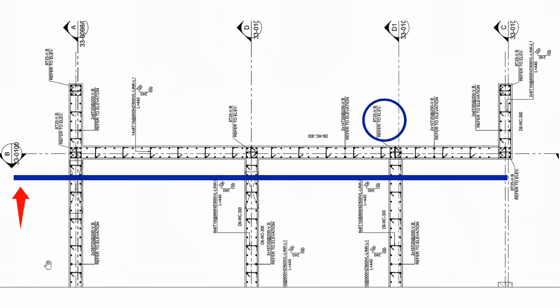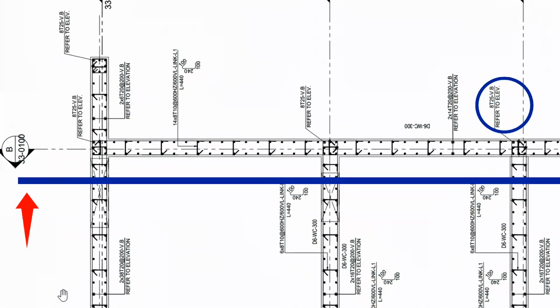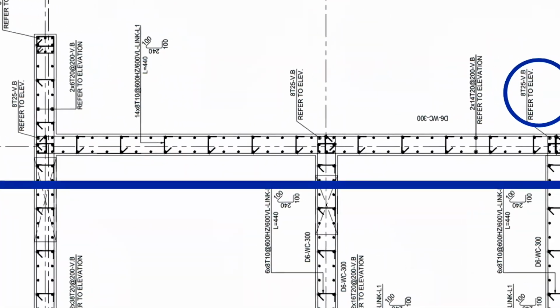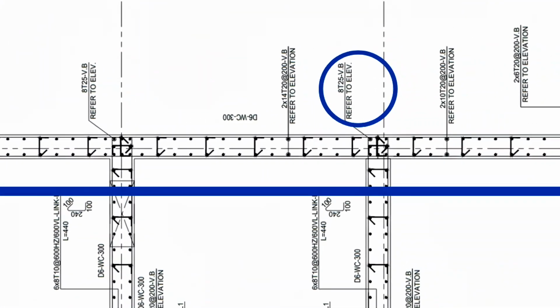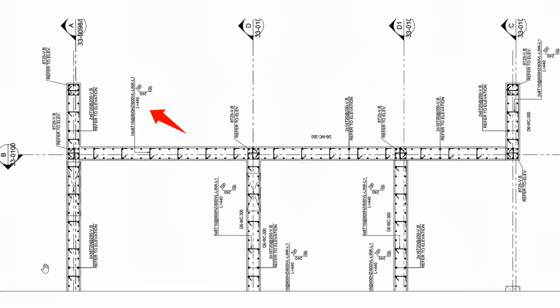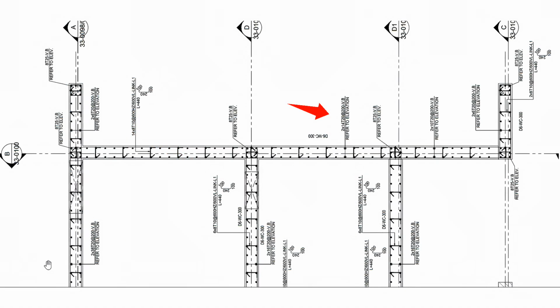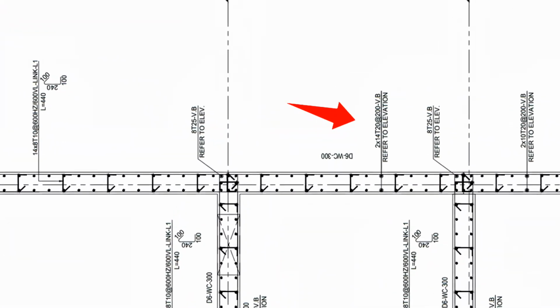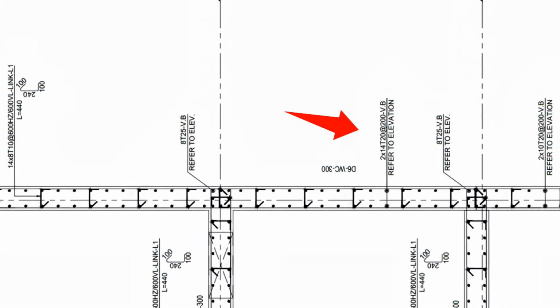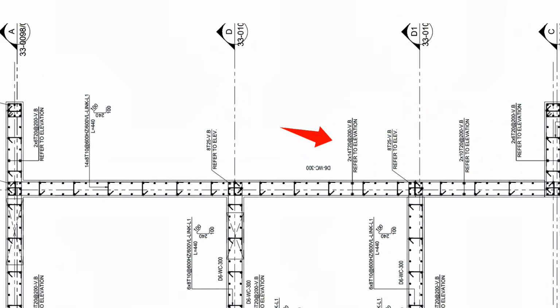Section B_B, steel reinforcement plan shows 3 columns, with each column using 8 pieces of 25 mm vertical bars, and the dimensions of the columns will match the wall. On both sides, 20 mm steel bars will be placed with a spacing of 200 mm. In the wall, link bars of 10 mm steel with a spacing of 600 mm, both horizontally and vertically, will also be used as shown in the drawing.